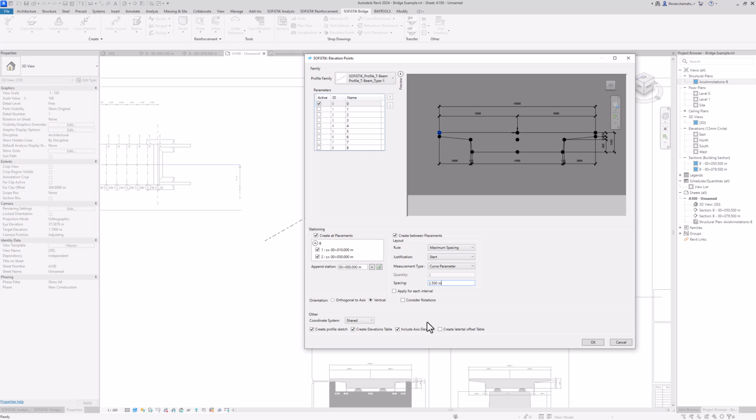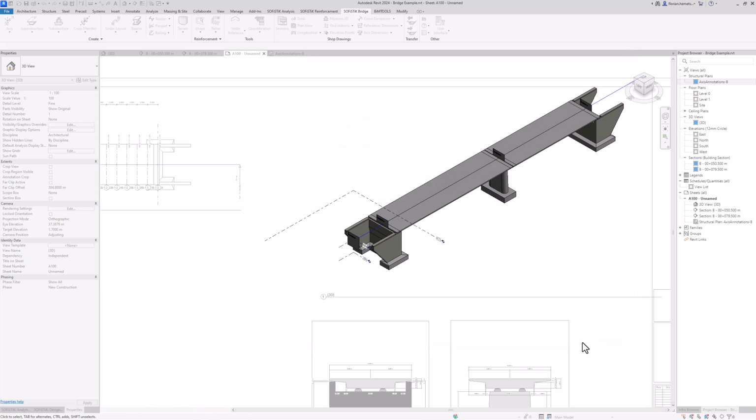Down here, I have additional options to create information. For example, the preset is only to create the axis height information as well as the point height information. But I could also output an X, Y, and Z table for the coordinates of this point. I can simply select it down here and click on OK.